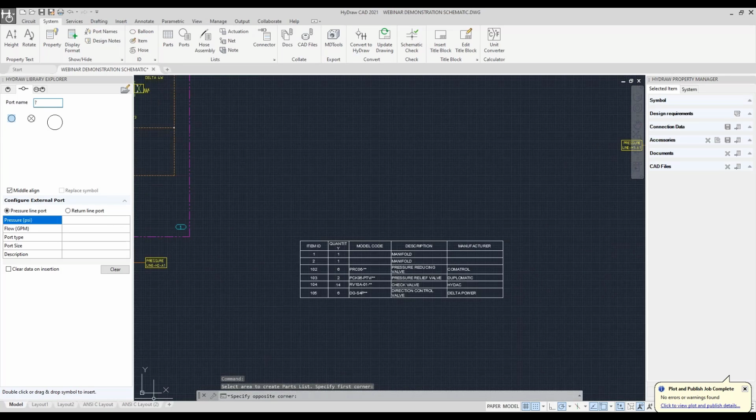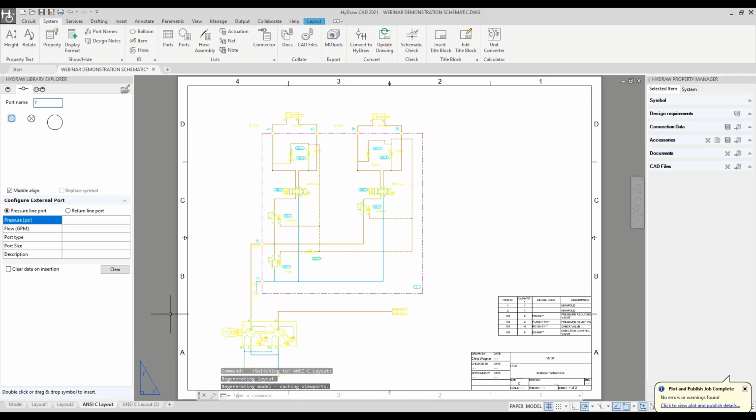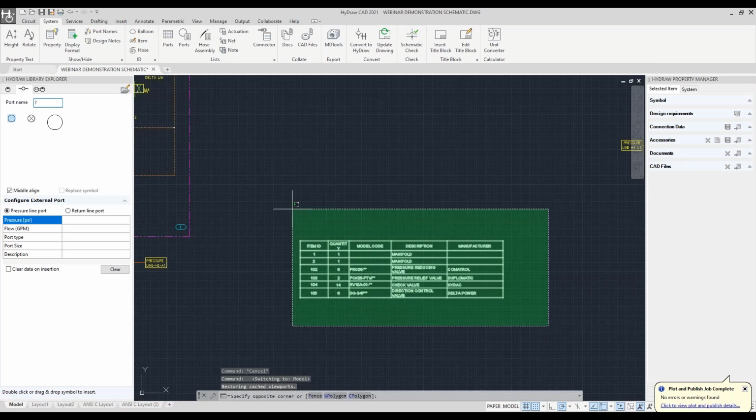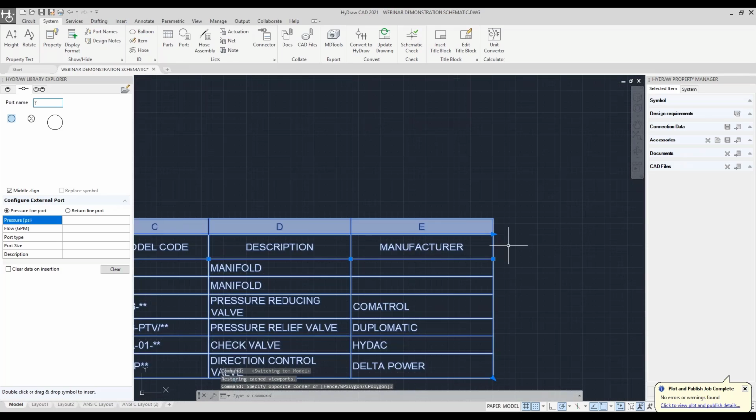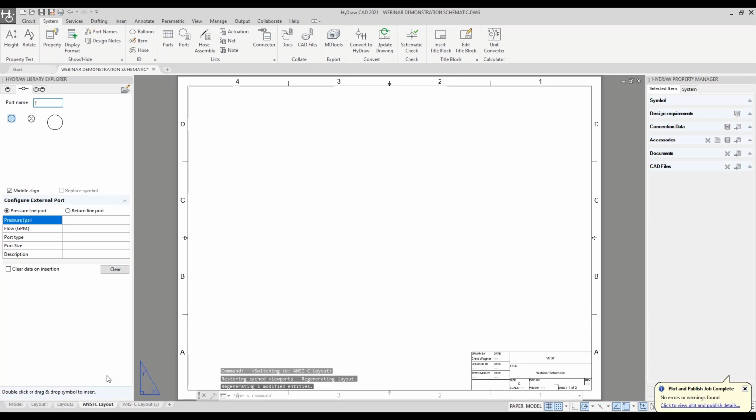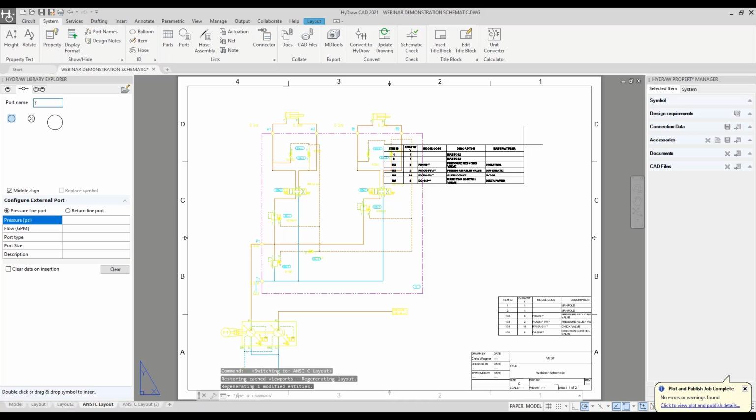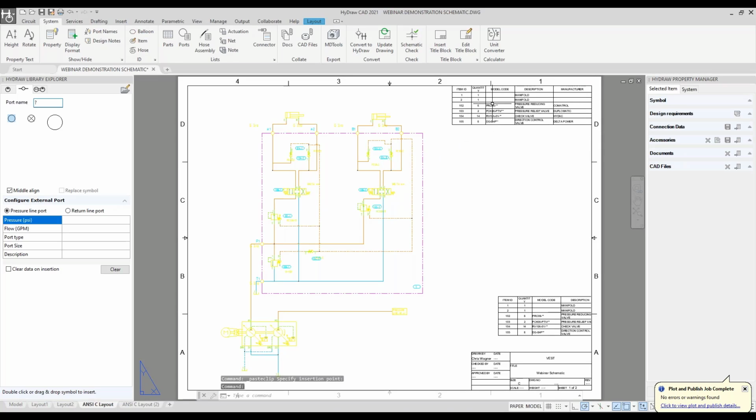Now, from here, if I actually go into our viewport, you should be able to see it down here, but that's not really what I want because this is technically part of the model space. Go back to model space, actually select this, and then there's a different type of copy command that we can use, which is Control, Shift, and C, which lets you pick a point where you want to select this from. So we'll select the upper right corner. I can come back over to my first drawing, and then just a Control V to paste. I can put that right up there. And so now this is technically part of the paper space drawing.